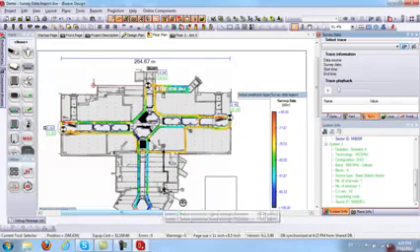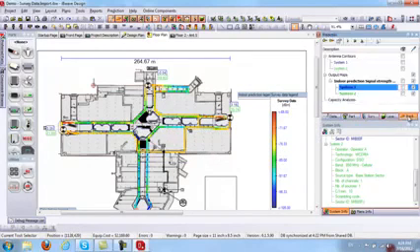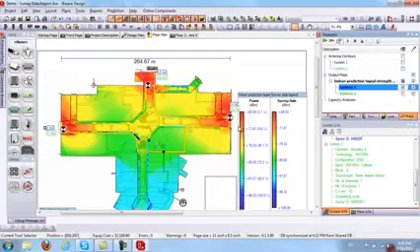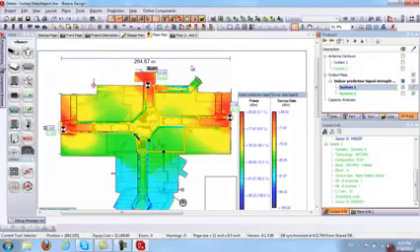So if you are using one of those measurement tools, you can simply import the .csv and map info coordinates file into iBwave design, and this will display your measurements inside the floor plan in the exact order they were taken. Then you can run your prediction, and once you do that, you will see the prediction versus measured data. And you can also generate a report that will show you more details on the prediction versus measured data. So the collection module is very simple, exactly like we showed here.